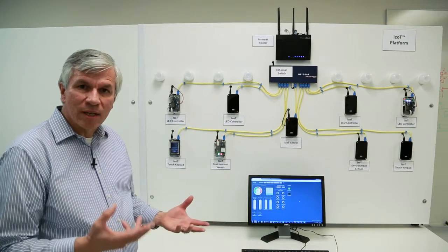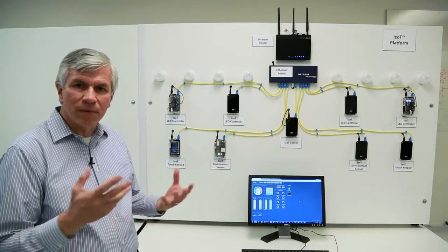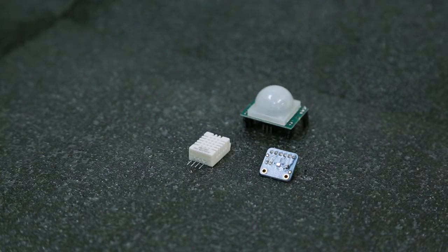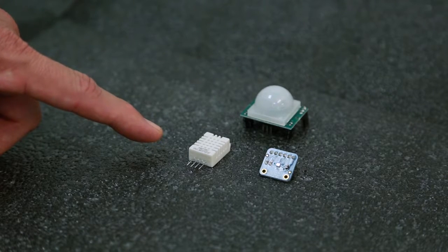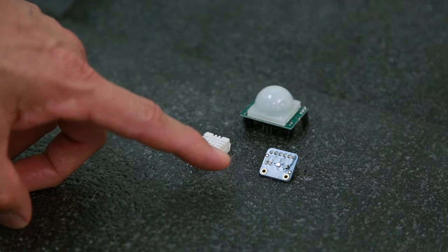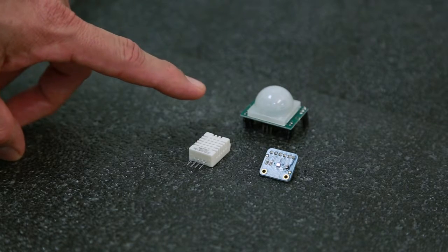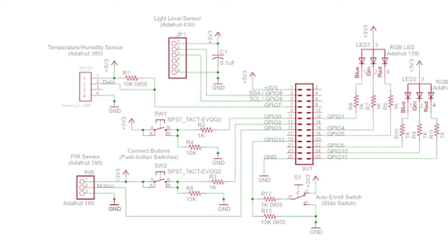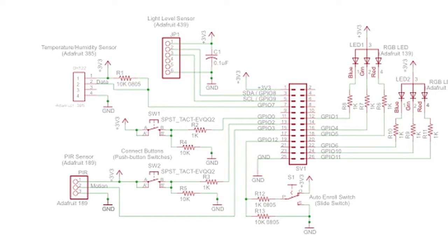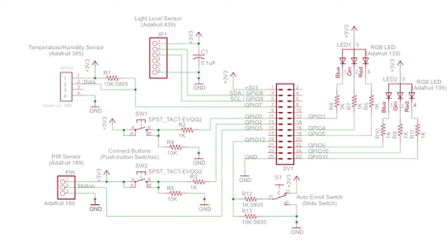The environment sensor senses temperature, humidity, light level, and occupancy of an area. To create the environment sensor, we designed the hardware as an I/O board for the Raspberry Pi, using sensor modules from Adafruit. We used a DHT22 temperature and humidity sensor, a light level sensor based on a TSL2561 light level sensor, and a passive infrared sensor module. We include schematics with the IzoT device stack for all the I/O boards that I'll describe today. For example, here is the schematic for the environment sensor.